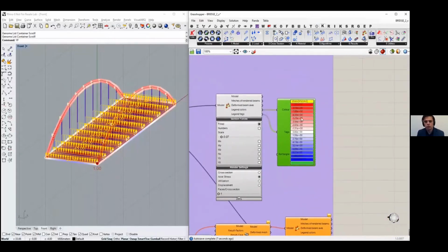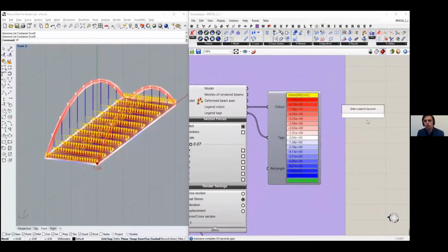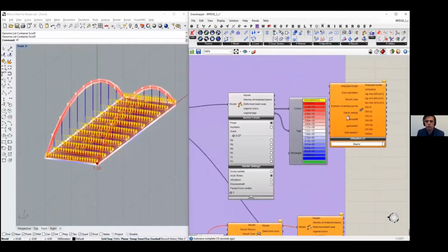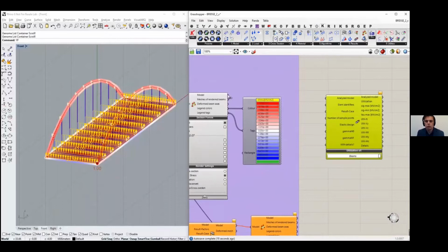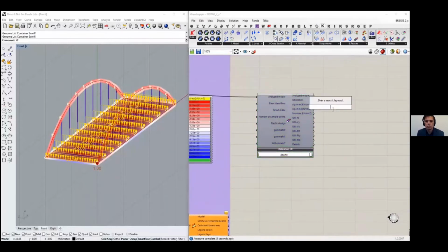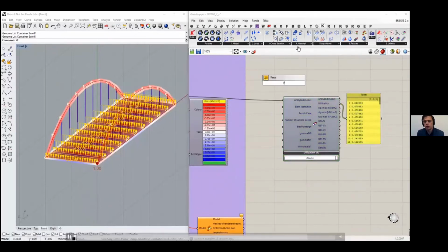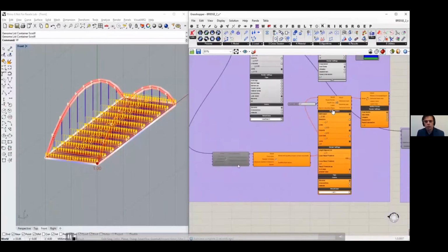Like that, when the calculation is done and I have forces, I can do the code check. So as I said, we can do the code check according to Eurocode 3 for steel members. So I just input the model and it's done. I already have the results. So the question is just how we view the results. In this case, I will just add the text panel. So I have the utilization ratios for all the members. So by those numbers before them, I can identify the members. And I can again use the identifiers, for example, and check just the arc members in this case.